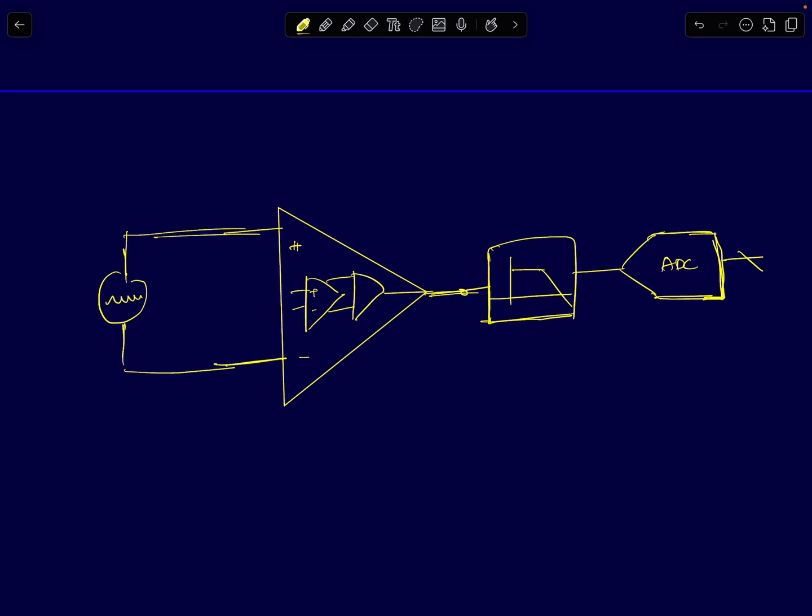That's the application of an instrumentation amplifier. So one example, then how do I pick the right one? I showed you a plethora of differential amplifier chips, and each chip had some specification: some chips had lower offset voltages, some chips had lower noise voltages, and the lower noise voltage chips were priced higher. So I thought I'll give an example of how noise matters by doing a calculation for an ADC.